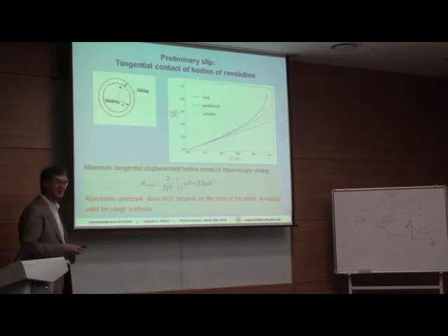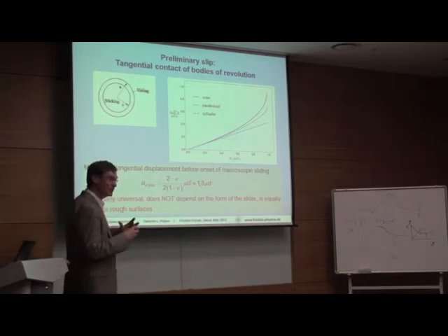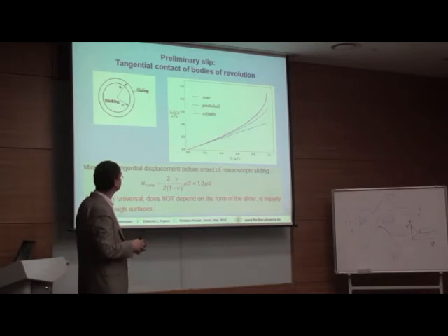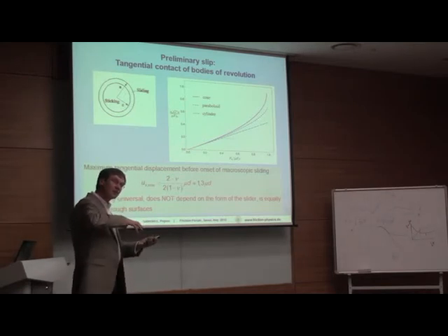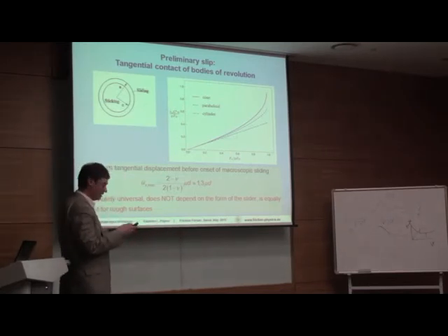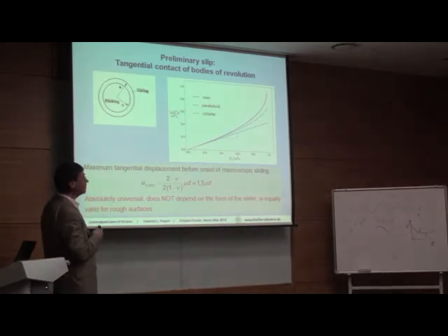But maybe first the second part of it, the preliminary stage. If you load the static contact, then there is some movement without macroscopic sliding, and only after some time it starts to slide. That's what is happening in fretting. Yes, it's fretting.